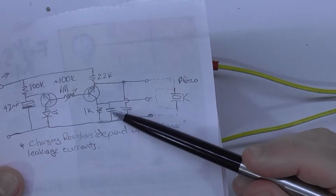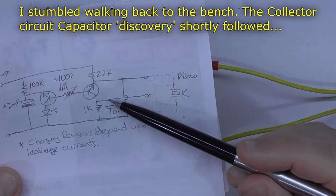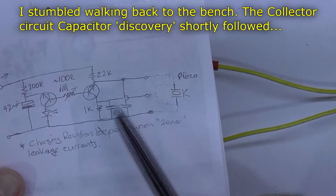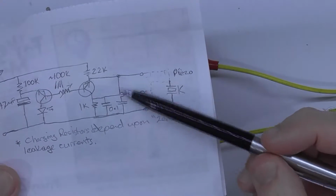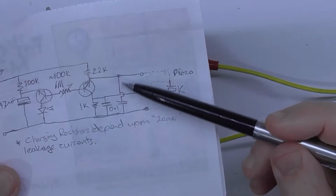And I literally stumbled on the fact that I could put a capacitor here in the collector circuit, and it would start to oscillate. Now the explanation goes along these lines, I believe. We've got two 0.1 microfarad capacitors, one in the emitter circuit, one in the collector circuit.